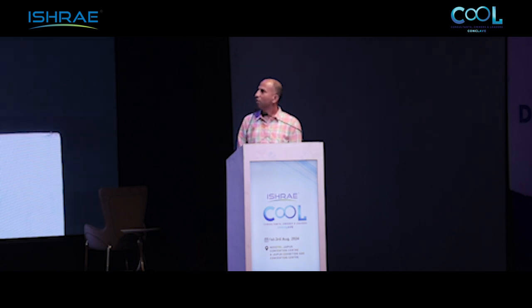Now, in terms of long-term refrigerant options for not-in-kind as well as vapor compression technologies, these are the 5 refrigerants that it boils down to: ammonia, a natural, widely available refrigerant having a proven track record; carbon dioxide, again an excellent environment-friendly refrigerant; hydrocarbons, they have their own flammability issues, but they balance it with the efficiency that they come across with.